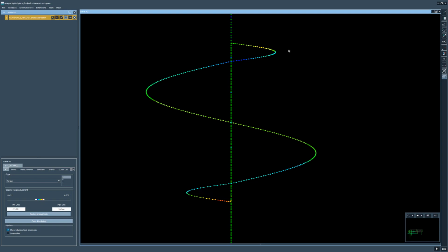Now what do we see here? We see that the X1 motor, as an example, doesn't have any torque, or not a lot of torque, let's say, when the drilling tool enters the hole, but at the very end the torque increases to like 6.3 Newton meters roundabout.